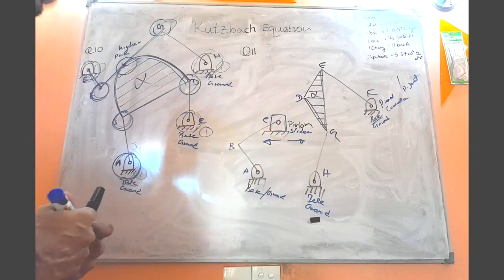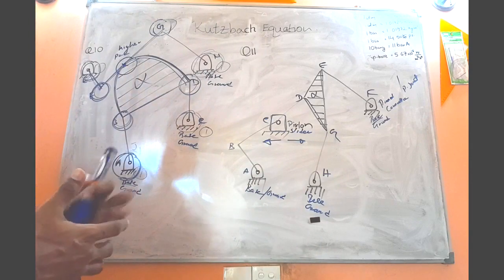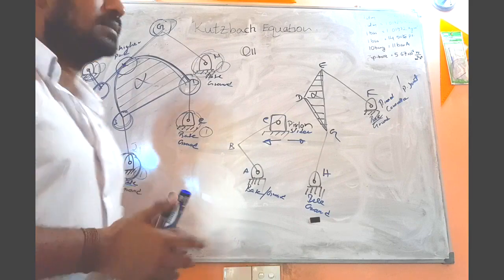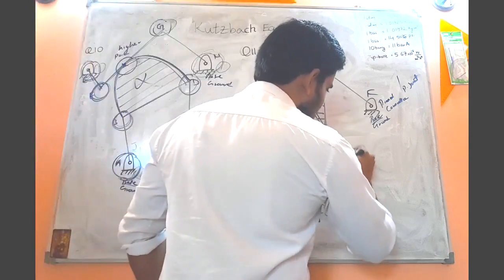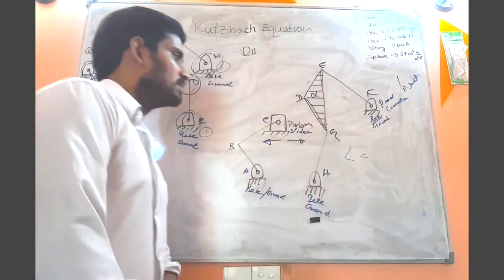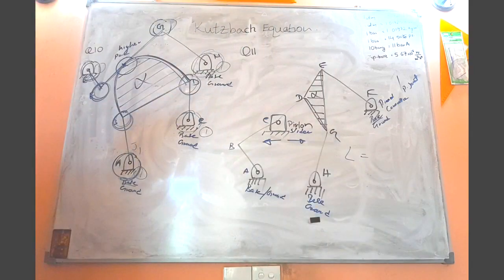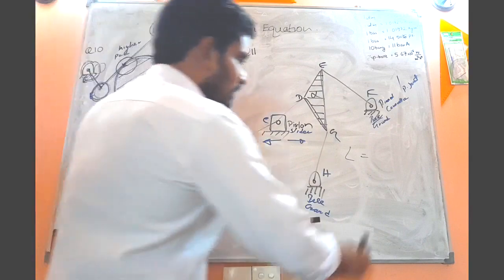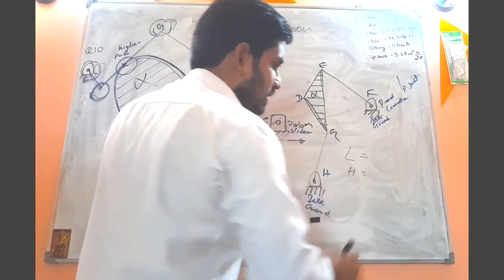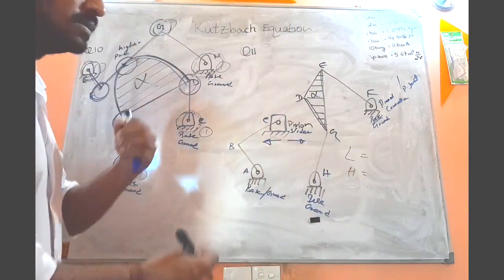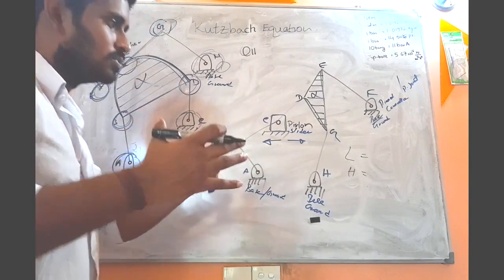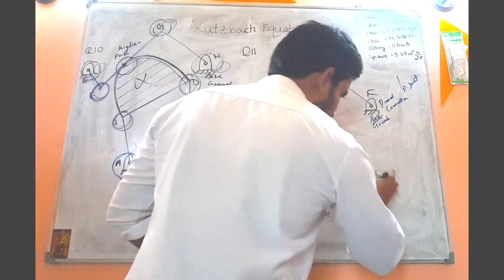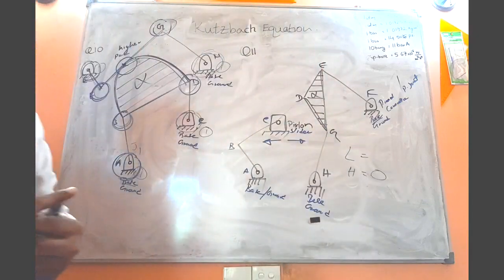Okay. Now let's label. What is the number one thing? We have to find the number of links, the number of members, and this question is very easy, right? Here, do we have any higher pairs? Do we have any connections such as tire rod connections or geared mechanisms? No, so no higher pairs. So H is 0. We don't have any higher pairs, right?